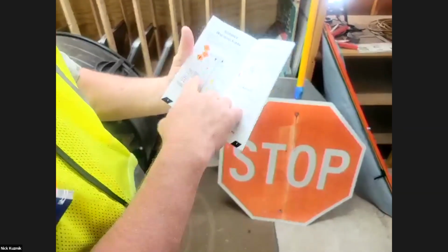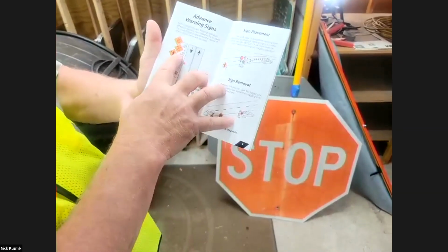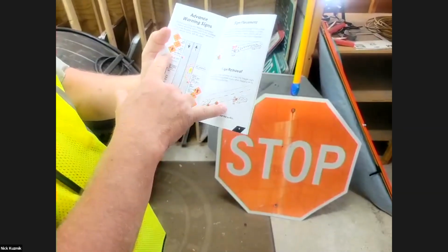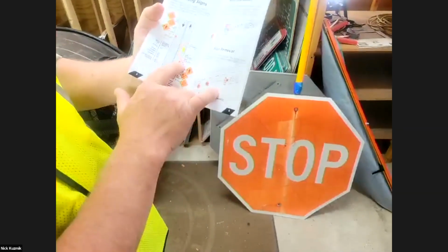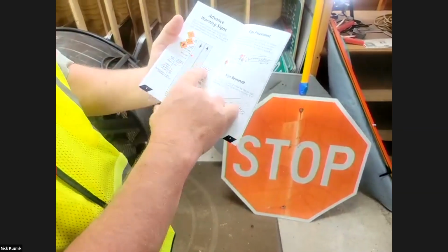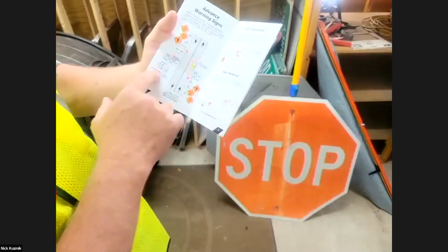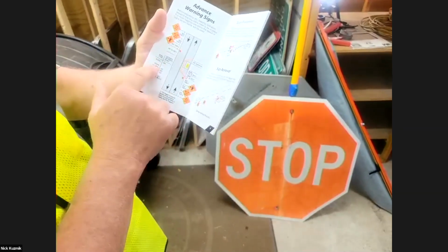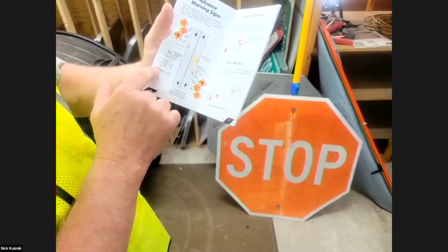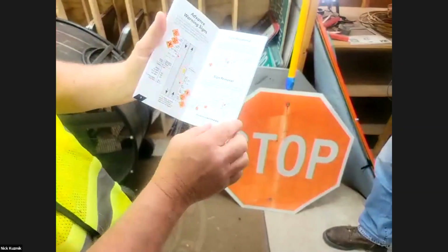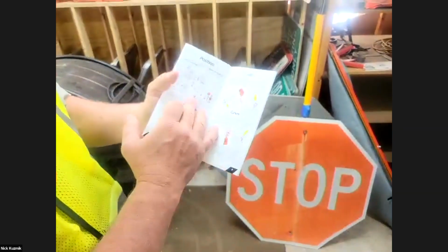Again, it shows us our work zone, our different signs: road work ahead, 1-lane road, then the flagger. So it tells you where the flagger needs to stand, gives you minimum distances, buffer zone, taper. And again, the distance behind the signs is going to be based on whether it's an urban or a rural area and the velocities of the traffic. So the sign placement, sign removal, it talks about all of this.